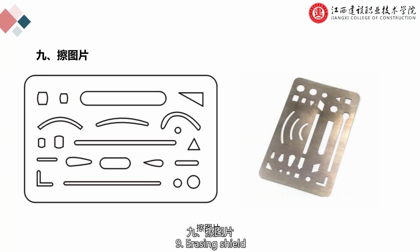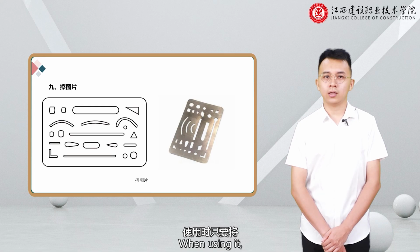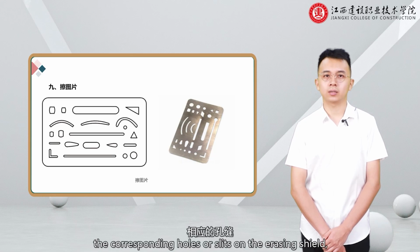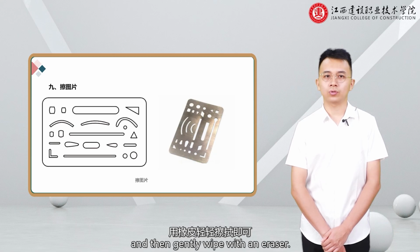9th, erasing shield. The erasing shield is used to modify drawing lines. When using it, just align the drawing lines to be erased with the corresponding holes or slits on the erasing shield, and then gently wipe with an eraser.